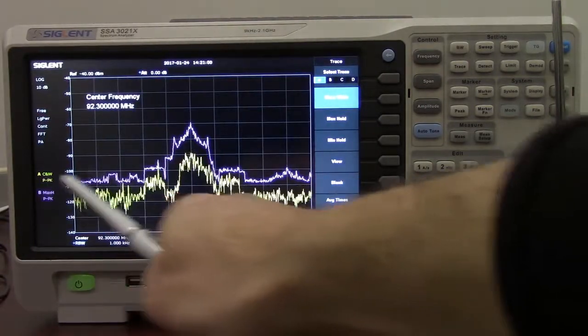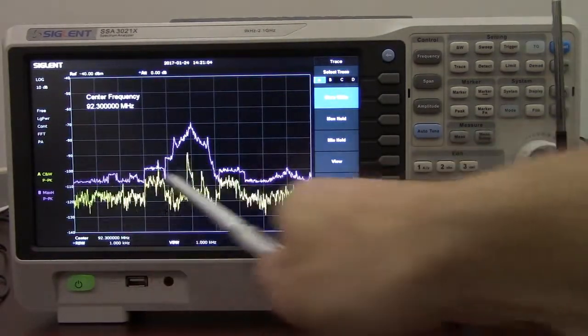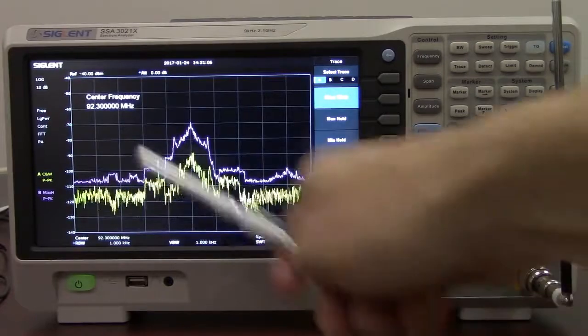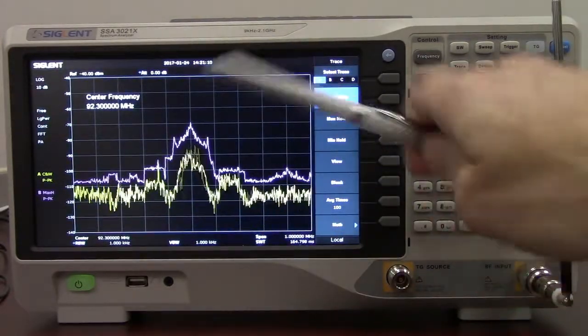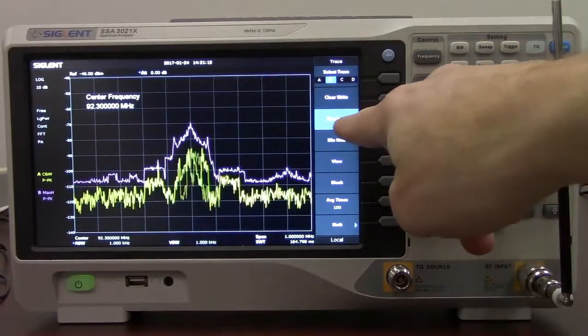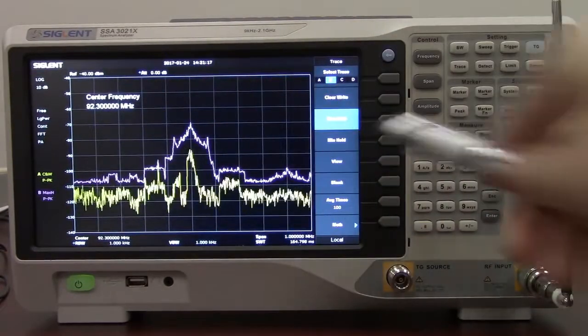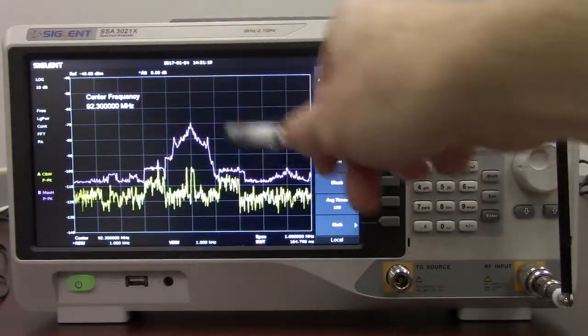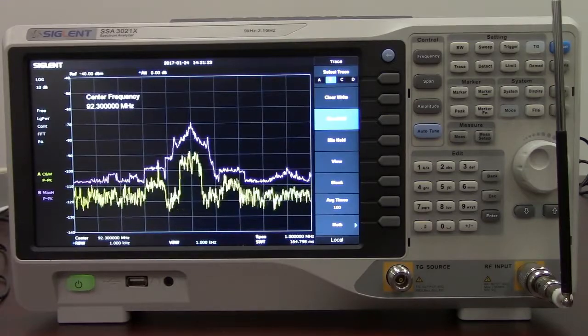Every time we've scanned through that particular frequency span, we're getting new values for each individual frequency bin. And purple here, which is B, is in max hold, and that max hold is going to show us the maximum values. So over a span of 10 minutes, we actually get the envelope that this particular transmission is also taking up.